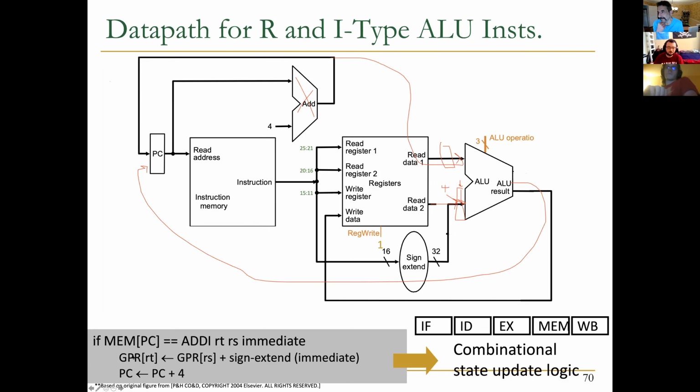But this could complicate things because, again, here we have 2 separate data paths. Since these are 2 separate data paths, we can safely do this thing and this thing at the same time, right? And you remember the discussion about this semantic. This needs to be written at the right time. When we fetch the instruction, if this is written quickly, this could mess with the semantic if we read this after it has been incremented, right?